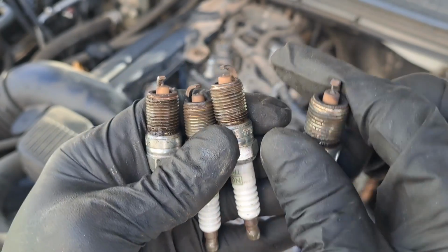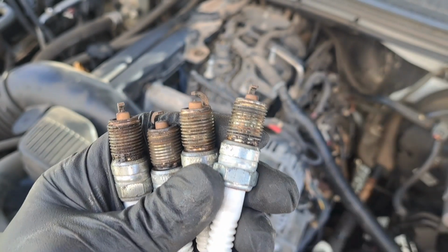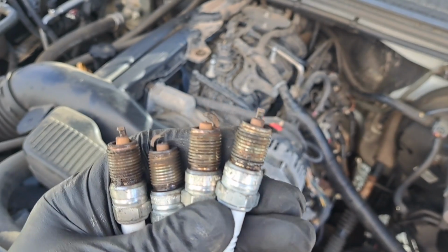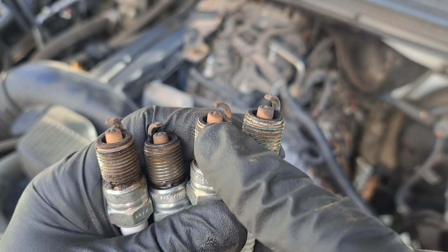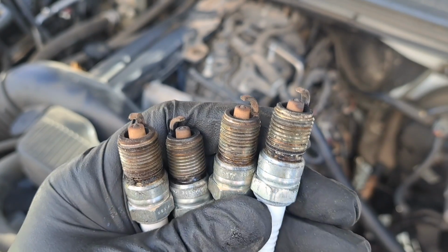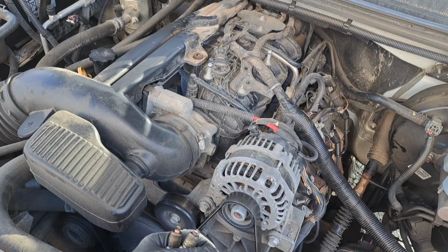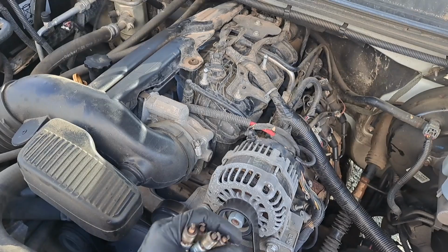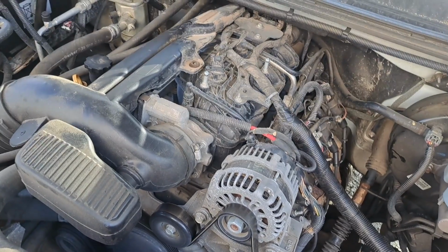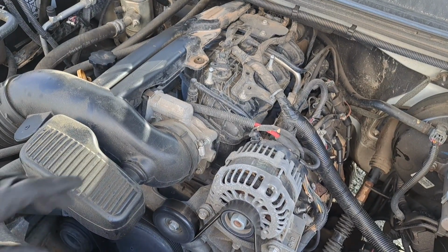And mind you, I do have factory wires installed. O'Reilly's did have AC Delco wires, but again, you can see the gap is very excessive, well out of the service limit. Typically they're going to be around 40 thousandths, but iridium's in there. You don't have to gap those. They're installed and everything went smooth.